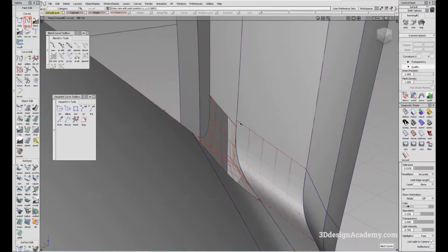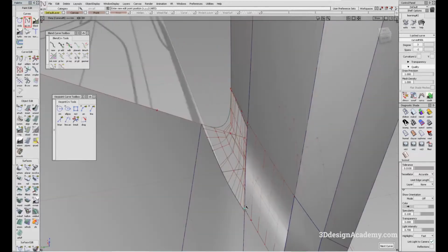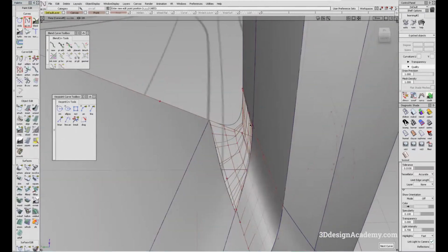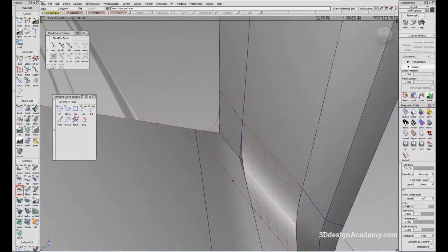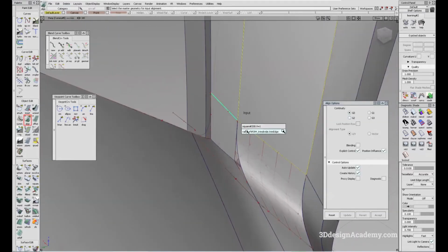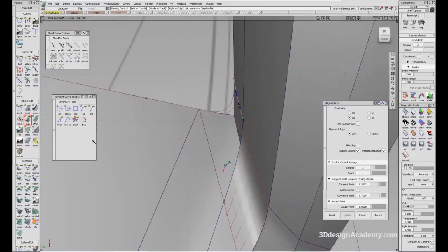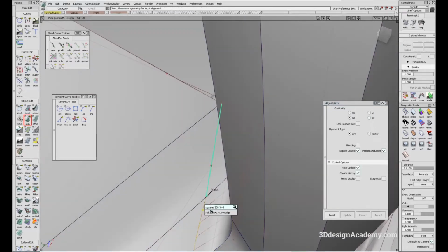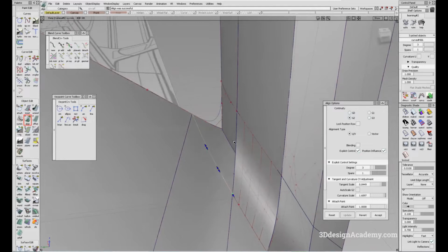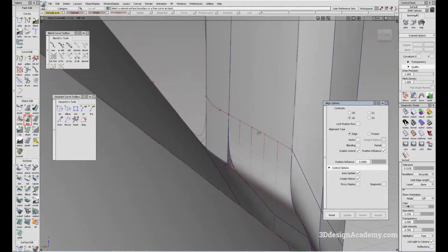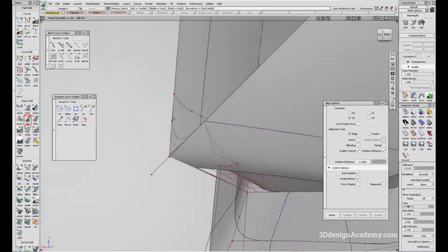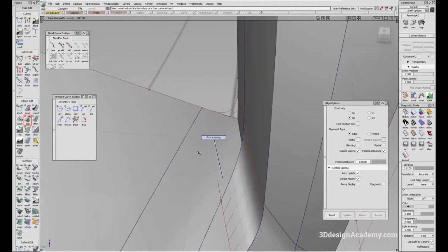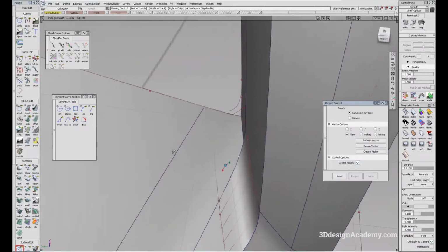Yeah, I think this is a good size. So what I'm going to do is I'm just going to create a degree 3 curve, connect the ends. I might have to do some adjustment, but we shall see how it turns out. So I'm just going to undo this one, and I'm just going to align this one like this, G2 here, and this is also going to be G2 curvature like this. Looks like it's not bad. Yeah, I think this going up is okay because the intersection point is also going up. So just going to leave it like that and use it as is.